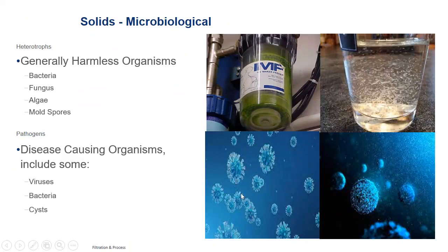This is a membrane technology, either UF or RO will filter out viruses from water. Same thing with cysts and bacteria. But those aren't foolproof solutions either. Remember, we're going to be constructing treatment trains based on the incoming water, not just a one-trick pony or the magic bullet of treatment. There is no such thing in water treatment.